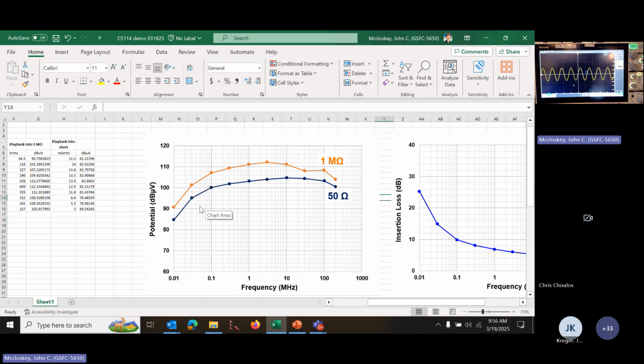Okay, so you can see that at 10 kilohertz we're fairly low, and then the levels come up and asymptote more or less above about a megahertz. It's pretty typical for these injection probes to level off right around a megahertz, and that's where the knee in the curve of the limit line is, which I don't believe I've ever seen written down anywhere, but I'm pretty sure that's by design.